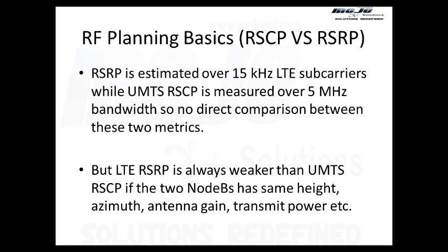The basic difference is that in frequency division duplexing, you have a separate channel for the downlink and a separate channel for the uplink, a separate frequency bandwidth for uplink. So in UMTS, 5 megahertz for downlink, 5 megahertz for uplink. Totally this is 10 megahertz for UMTS, but we say the carrier is 5 megahertz because downlink is 5 megahertz only, and uplink is 5 megahertz. But in total, the frequency being used is 10 megahertz.